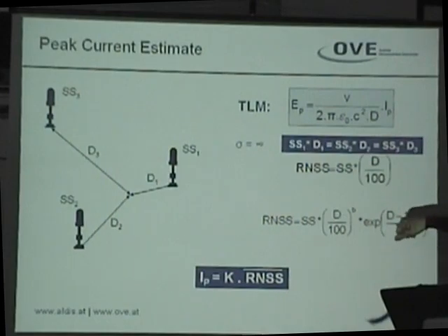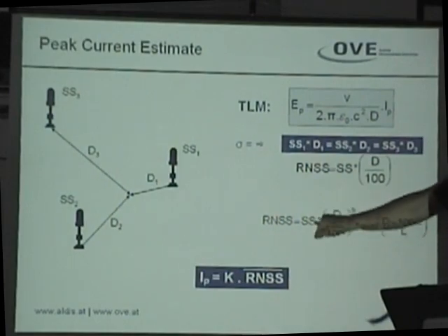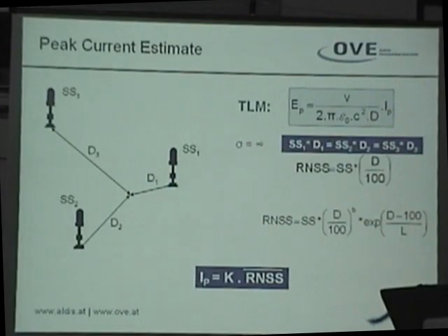And therefore, a different version to calculate the range normalized signal strength is used. Originally, up to 3 or 4 years ago, in the NLDN, this version was used with B equal to 1.13, and now they changed to this attenuation factor, so they use B 1.0 and put in here an L of 1000, because with this version of attenuation, the individual sensors fit better to each other.